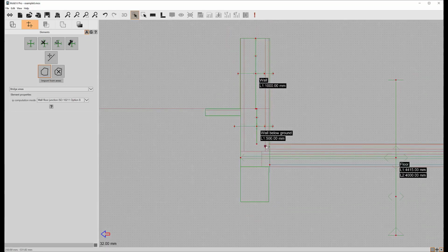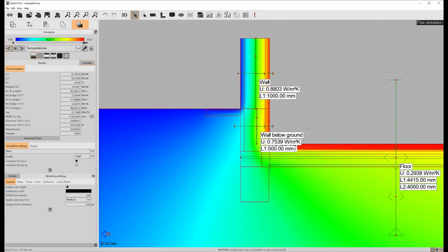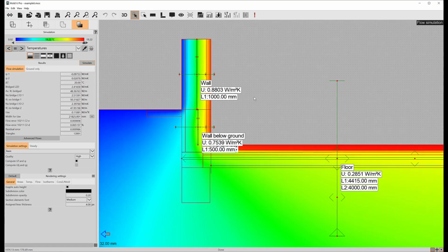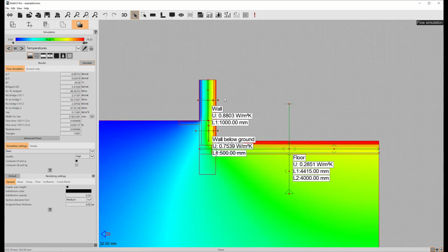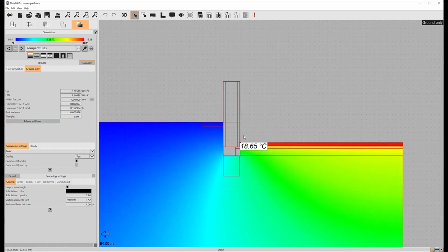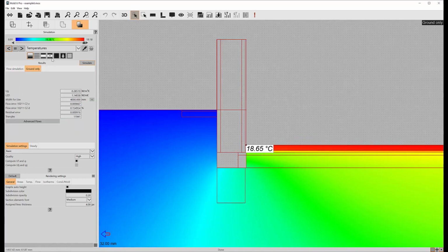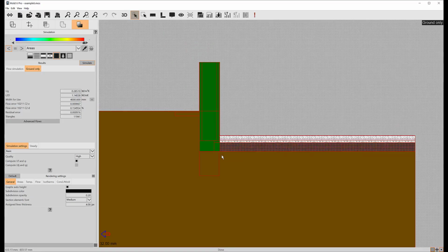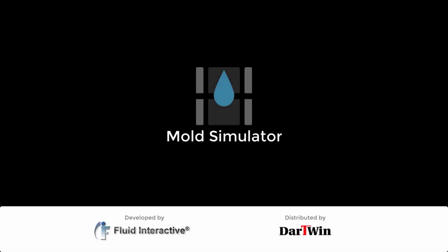We're now ready to compute PSI values with the ISO 10211 option B method. Results are very similar. Note: a ground-only simulation ran to get the UG value. The wall has been replaced with adiabatic material, and the other elements have been replaced with ground material.